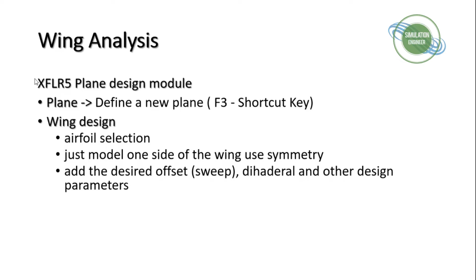One has to make sure that you cover all the polars of your Reynolds number, because in the case of a constant chord or a tapered chord, you will have different Reynolds numbers locally along the span of the wing. So one should make sure to do the complete flight envelope to get a properly converged solution once you are doing a 3D wing analysis. We will see how I have defined the wing design parameters and the airfoil which we will be using here.